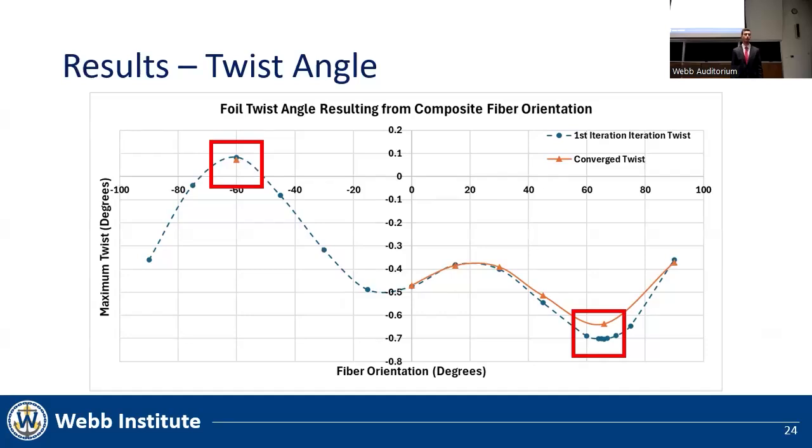This means that a positive 30-degree layup is not equivalent to a negative 30-degree layup in terms of overall stiffness and deformation response. Additionally, hydrodynamic forces acting off-center can further amplify asymmetry, making the foil's response differ significantly depending on fiber directionality.